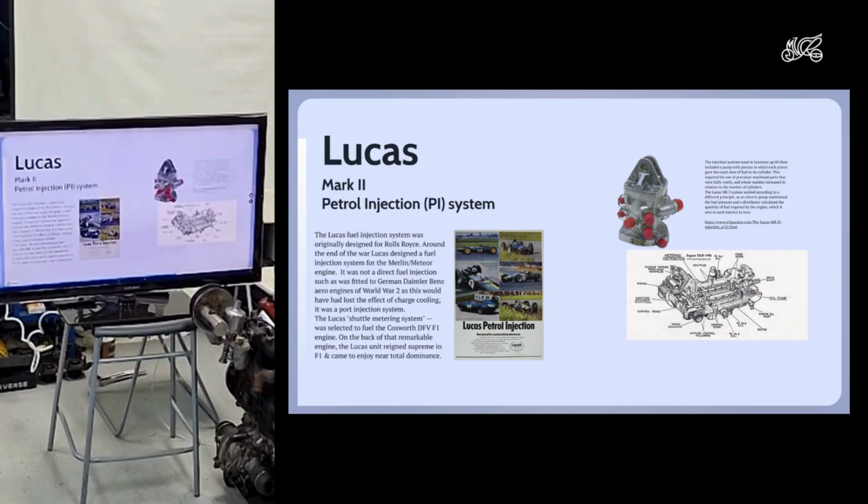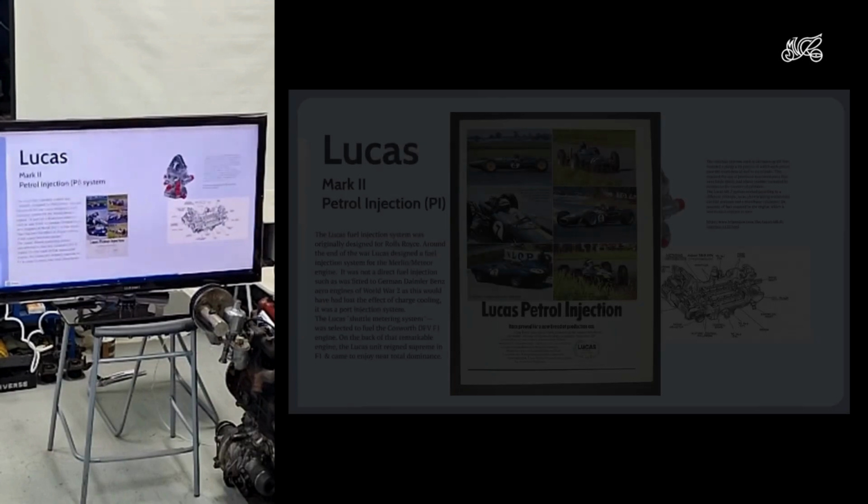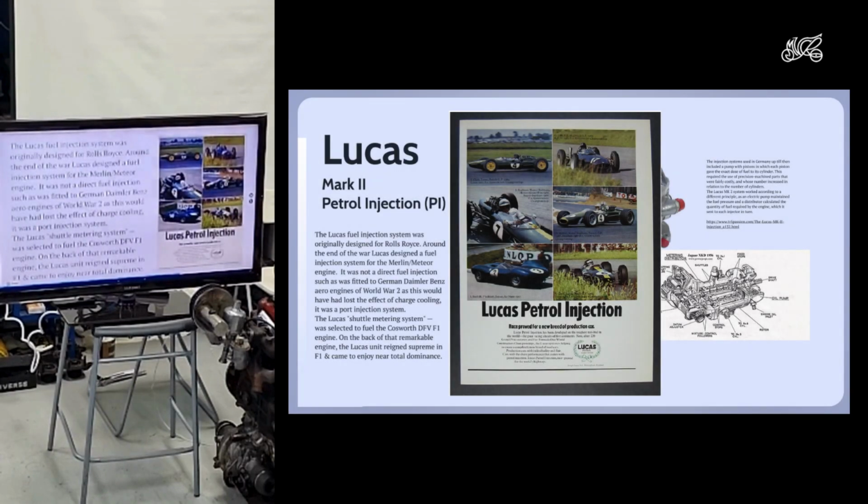These pumps were pretty successful in their period. This advert here, I don't know if we can zoom into the ad. Yeah. So this was the race car injection system of the 1960s. So they were quite popular. It turns out these pumps, their design, were very sensitive to the lubrication in the fuel. And as we went to unleaded fuel, the lubricity of the fuel dropped. And it turns out these pumps had lots of problems in the 1980s and 1990s because of lubrication weaknesses.